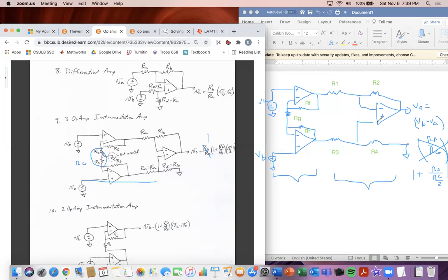But you guys can just do instead, because he should have had a 1 plus because it's a non-inverting amp. You guys can tell it's hooked to the positive terminal. And so his note was wrong a little on there. But this is the equation you should be using. I suggest use this model here provided in his notes over the one he did in last lecture. And this one I just find simpler. But let's go back now to number 7.